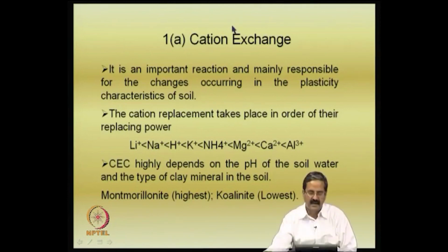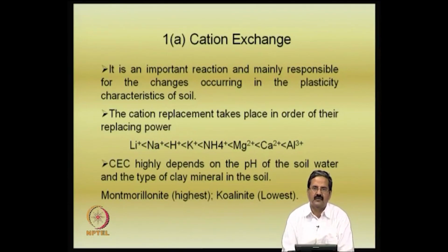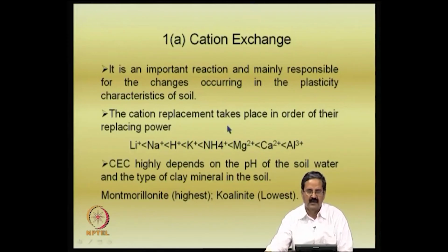We will see what cation exchange is. When you are dealing with soils, particularly clays, cation exchange is an important aspect. We know that clays have negatively charged surfaces, and when you add some material like lime, there is a replacement of ions.